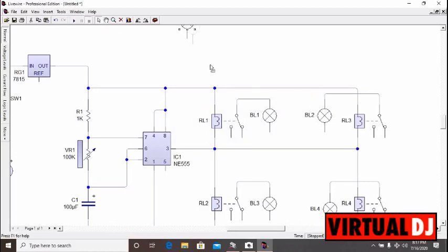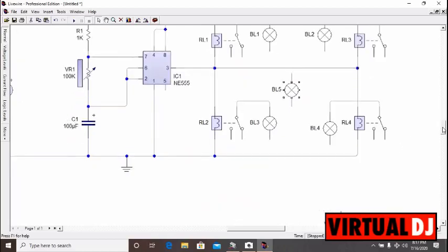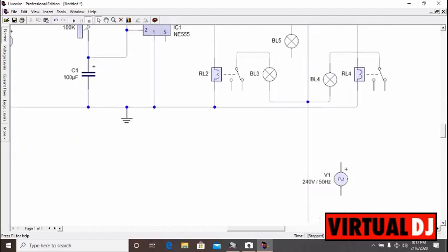Okay, then the next, now the pin 5, which is the bulb 5, sorry, I'll be connecting directly to my AC supply because it's going to be the middle bulb, which is going to be constantly on no matter the direction of display. Okay, before that we'll be looping the negative terminals of this bulb together, bulb 2 and 1. The negative, that is the neutral terminals. Then I'll be connecting the 2 neutrals down to each other here, then connecting from this spot down to the neutral of the AC